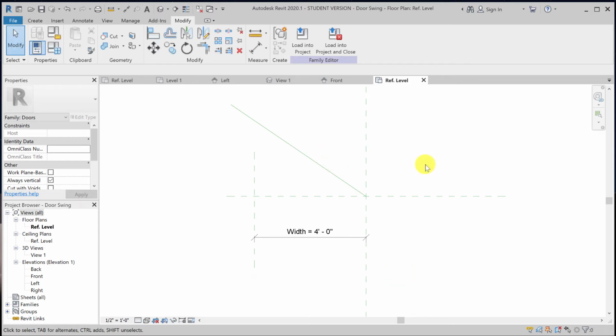Now for the remainder of this video, I want you to pay special attention to the steps that I'm taking to create this family. Okay, because whenever you're dealing with angle parameters, the order in which you draw each line and the order in which you place constraints to any object matters. Okay, so we might run into problems. I'm not going to edit it out so that you can see how finicky it is when angle parameters are involved.